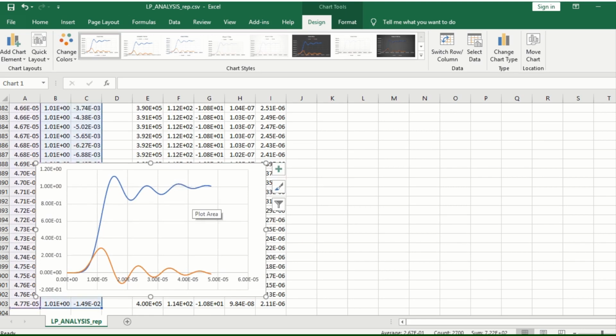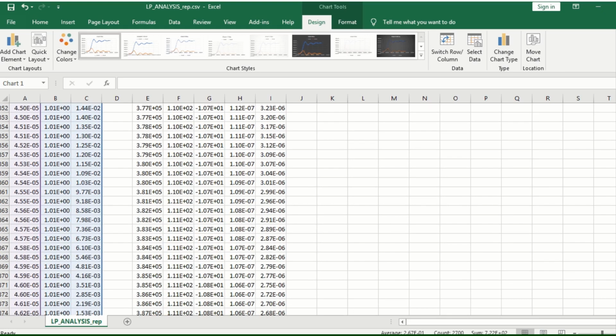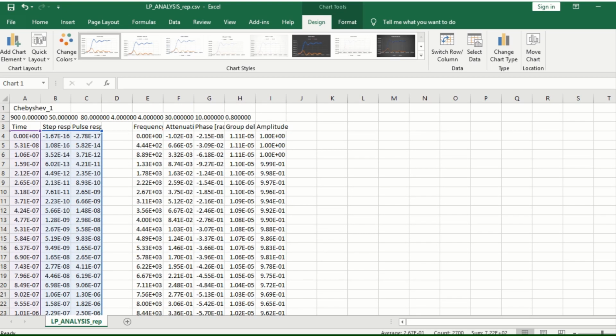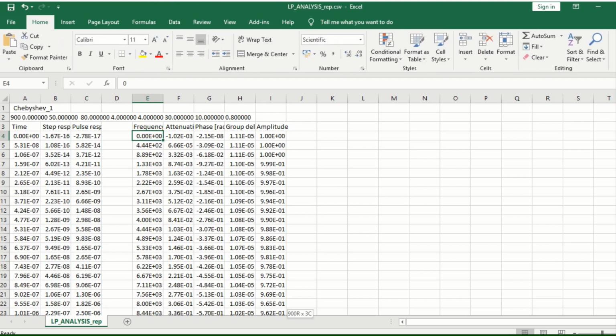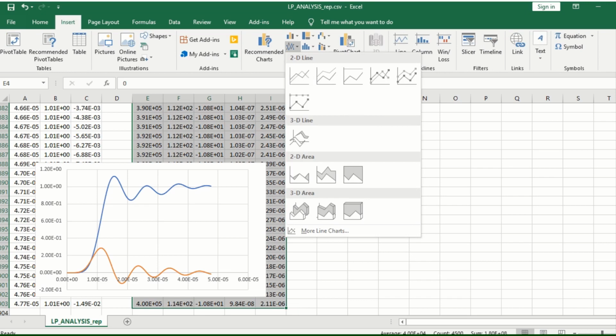So, by the way, we may see that the Chebyshev filter, or filter which have lobes at lower frequencies, have a very large undershoot which narrows the eye diagram when implemented in pulse transmission. Then we will go for the frequency domain analysis. And we will get here